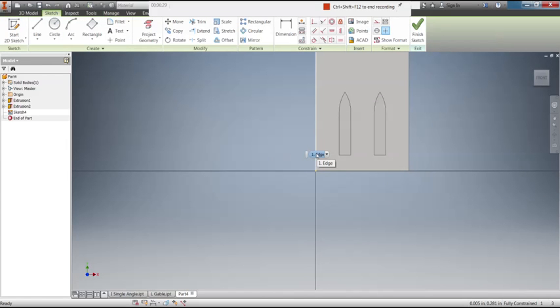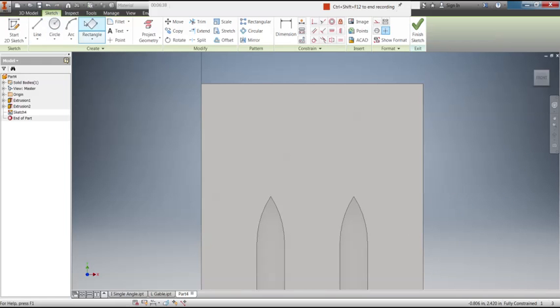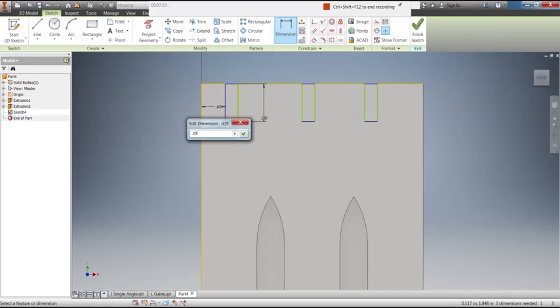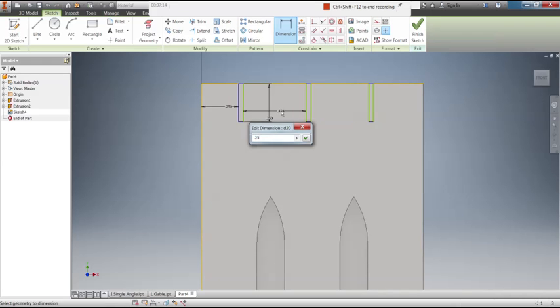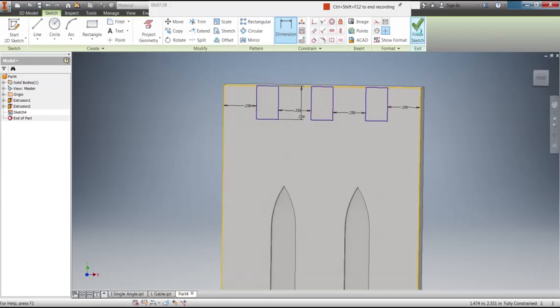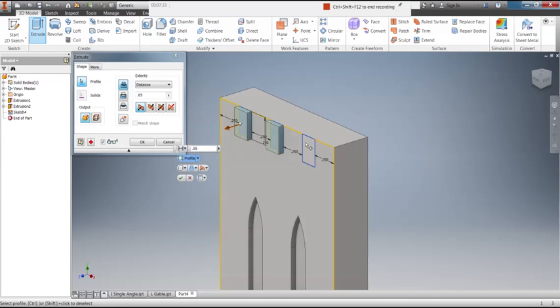Similar to the tower of the gable, there are 1/4 inch tall and 1/4 inch deep, and there's 4 of them. So I'm going to draw rectangles for what's going to be cut away, but dimension the spaces for what's left. So I need 3 rectangles here. And now dimension is going to be 1/4 inch tall. They're all going to be the same. And I'll set all these 3 to be equal right away too. But then when I dimension them, it'll work out. So I want this to be 1/4 inch here, 1/4 inch here, 1/4 inch here, 1/4 inch there. Now I can extrude those as a cut all the way through.